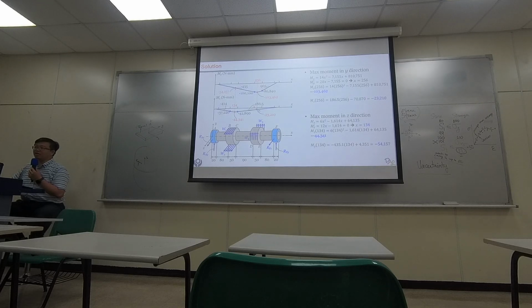Okay? So I even plug in the values at position 1, 3, 4 and position 2, 5, 6. I realize overall, I can compute the moment total. So how do you compute the moment total? Basically, they are moment vectors along 2 directions. So what you can do is a vector addition. Take the square of this plus the square of this one, sum them, and then take a square root. Then you get the total moment.